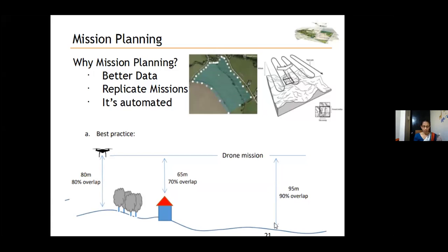So you have to take some precautions based on your terrain type. That's what I want to tell you. We have to plan your missions carefully. You should check all other important things, for example, whether there is an open area for takeoff and landing. Especially, it is very important if you are using a fixed wing drone, because a fixed wing drone needs at least 100 feet of area to launch. And also, a fixed wing cannot avoid obstacles in its path.